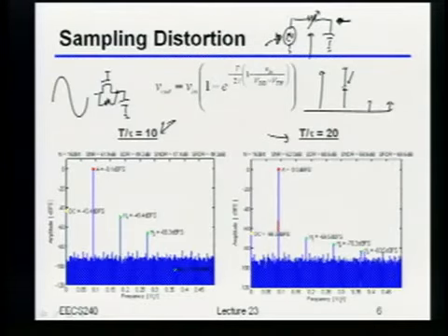If I decrease VN, what's going to happen? SNR. Yeah, basically I'm going to have more noise, which effectively is going to mean I'm going to have to pay more power because I'm going to have to increase the size of the cap. Right? So for both of them, it's bad news because it just costs you more power to do the same thing you used to want to do.